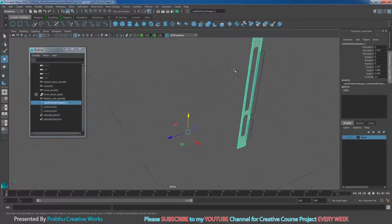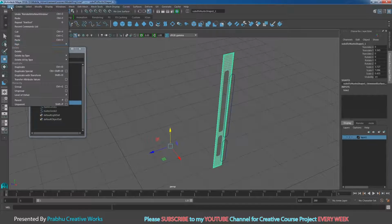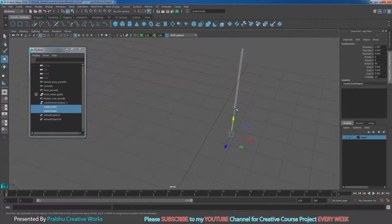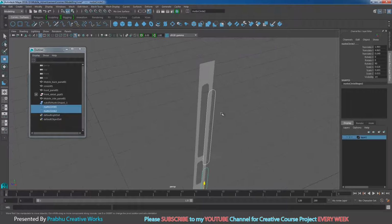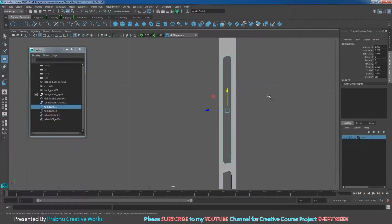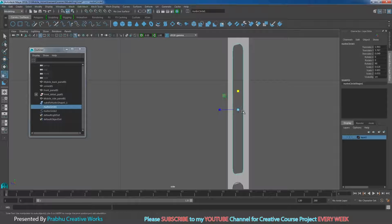So now I want to select this object. Go to edit, delete by type and choose history. Now I select both objects. Before that, select this object, go to right view. Now I want to scale it a little bit smaller. So press R and scale in a little bit, and scale in Z a little bit. Like this. Like this. You want to do this for this curve also.